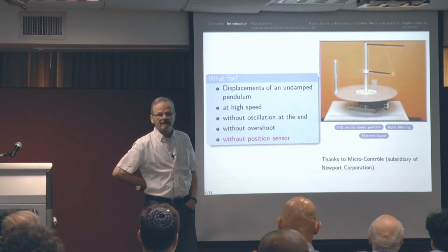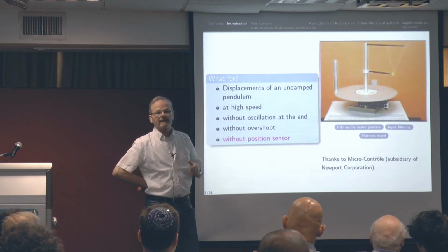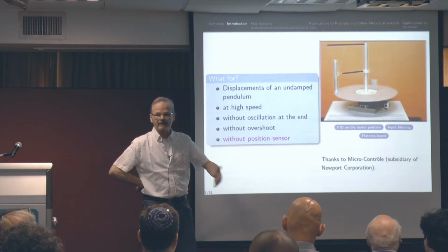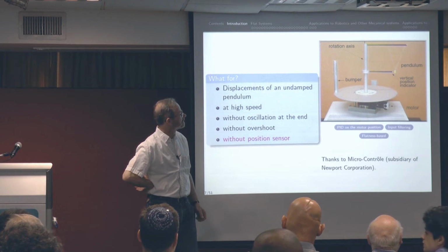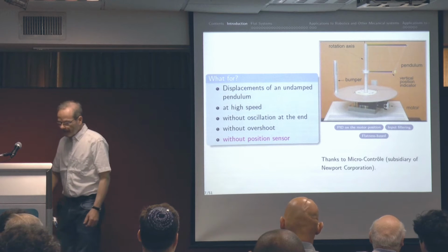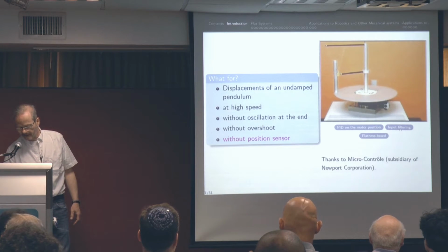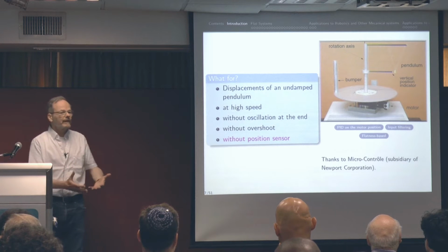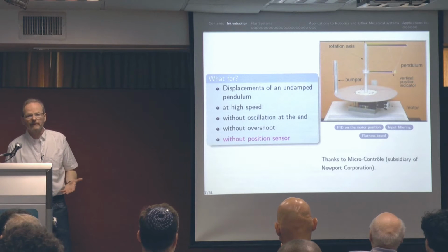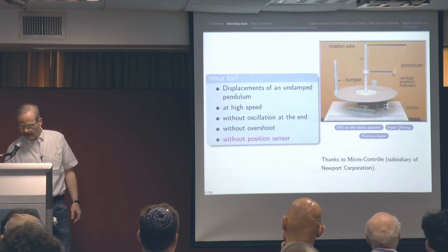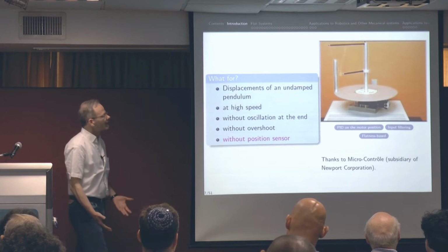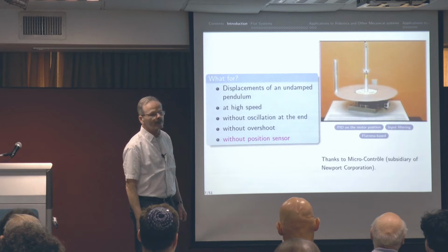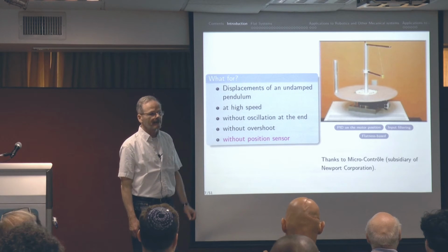Okay, so you can choose trajectories in such a way that you start at rest and you arrive at rest, at the same overall velocity of displacement. There are also other techniques, like input filtering, in order to prevent unwanted oscillations of the system. But if you apply that, that means slowing down the system significantly. The velocity here is divided by 4 in order to get the same amplitude.